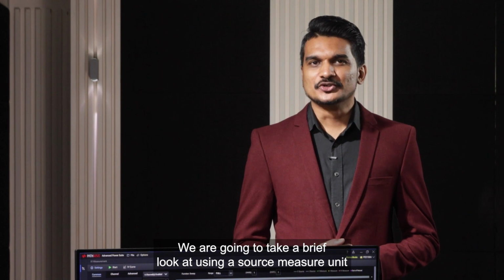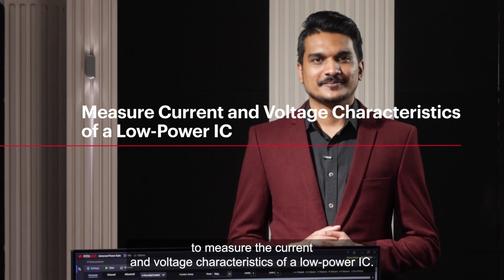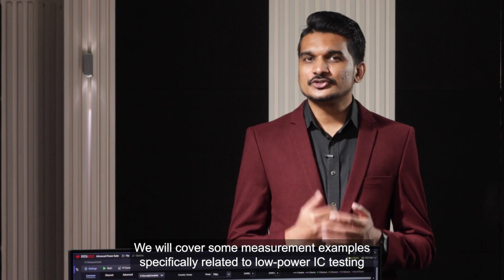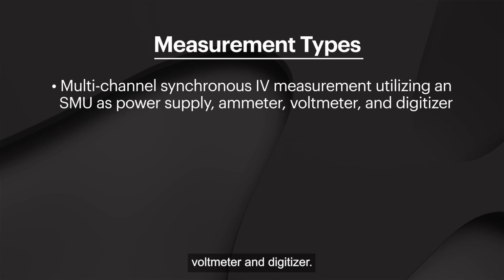We are going to take a brief look at using a source measure unit to measure the current and voltage characteristics of a low power IC. We will cover some measurement examples specifically related to low power IC testing, such as multi-channel synchronous IV measurement utilizing an SMU as power supply, ammeter, voltmeter and digitizer.